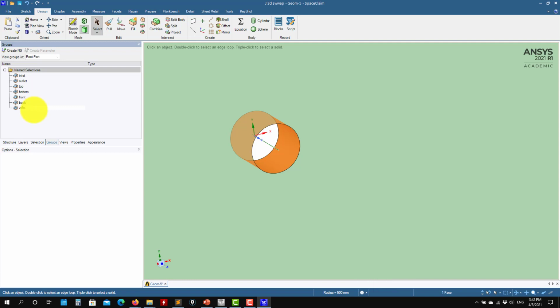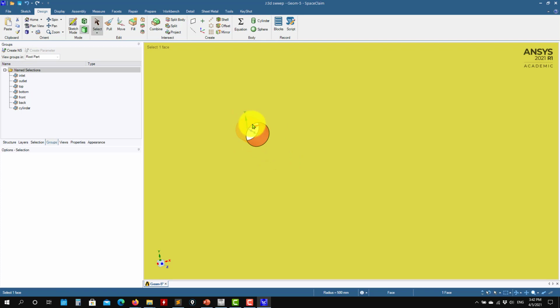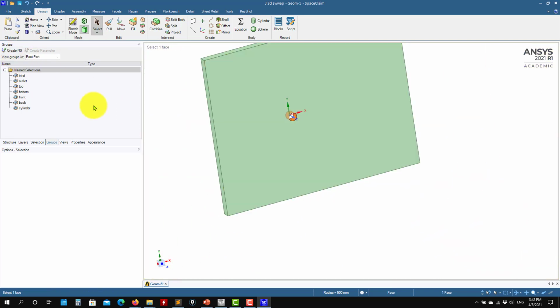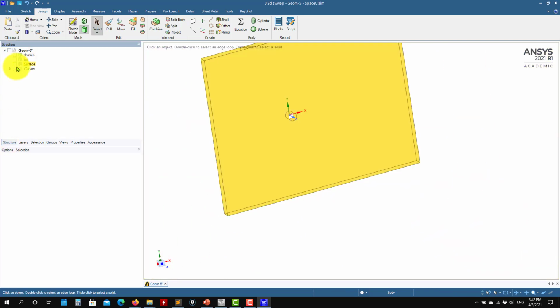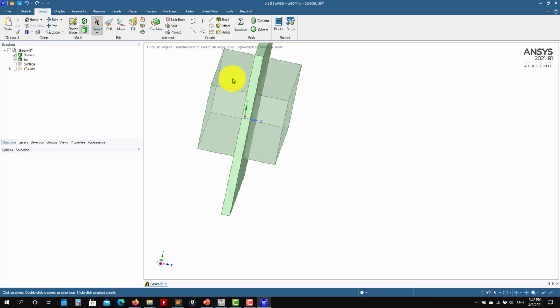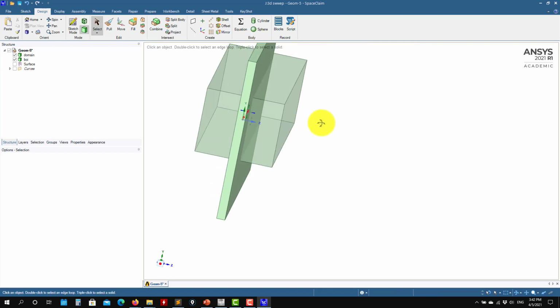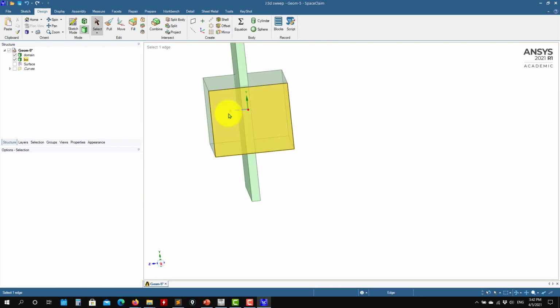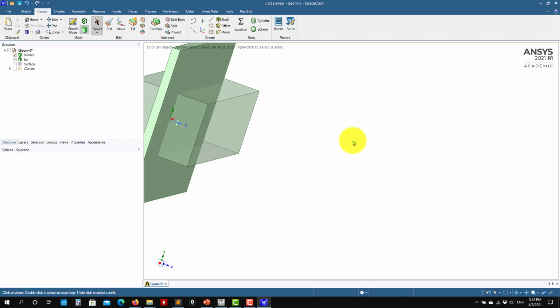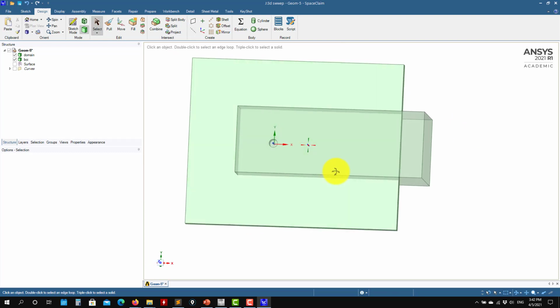Okay, see. If you do it in 2D, just to remind you, this will be a line. Here now you have a surface and you can get an idea that visualization is much easier. The body of influence remains the same. Everything within this one will be refined according to a criterion that you're going to give later. Again, it doesn't need to have the same dimensions as your domain. You can put it larger. It will just tag whatever cells exist inside. So that's what I wanted to show you here.